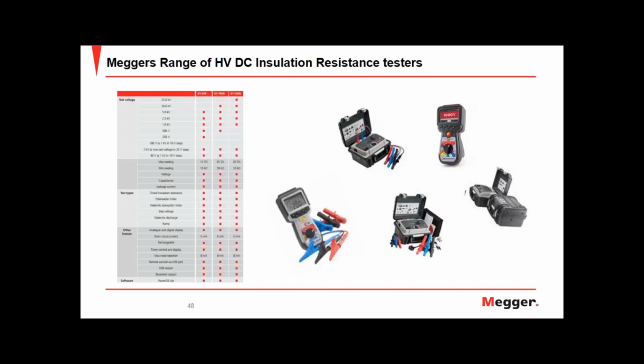Then we move up to the top right-hand corner, one of our most recent additions to the Mega stable. We have the MTR 105, which again is a handheld tester to 1000 volts, and this is primarily aimed at AC induction motor testing, but also other rotating machinery, again equipped with the guard terminal. And then we have the S1. The S1 is available in 5, 10 and 15 kV outputs. Our 15 kV output provides you with the ability to test up to 35 teraohms in a portable unit.